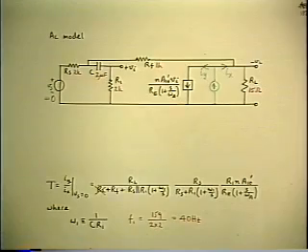One of the applications for the extra element theorem is, even when you know everything that's in the model, maybe you can simplify the analysis by dropping one of them out and putting it back in using the theorem, which is especially simple if the model is resistive and there's one reactive element, because then you get the corner frequencies directly.